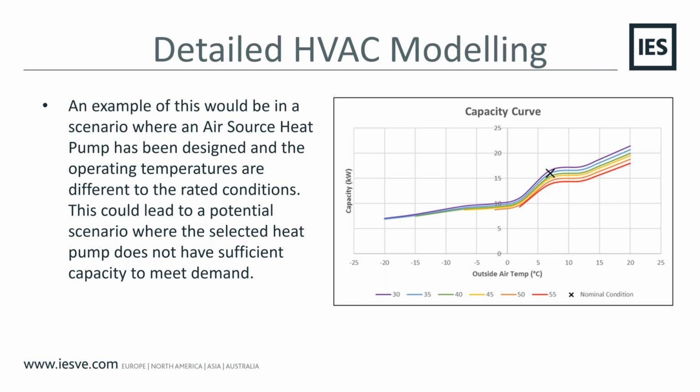Now, what we'd want to ensure is that the heat pump that gets selected for the job can not only meet the capacity at its rated conditions, but can also meet the design conditions based on the design temperature for the system and the design ambient conditions for whichever site.